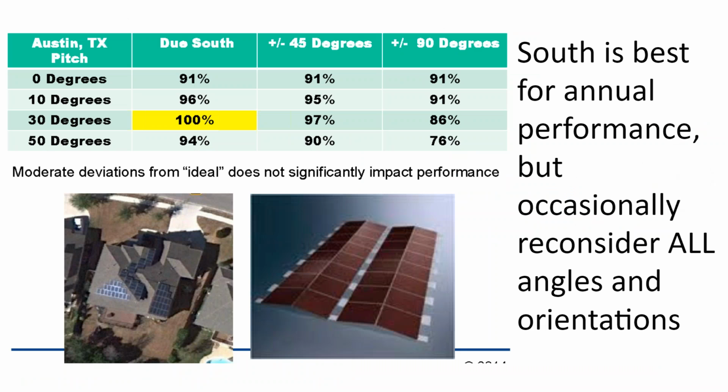And you say, well, JR, you're saying 1 watt will produce 1.4 kilowatt hours, but what about how you point the array? Doesn't that vary the production? And the answer is yes. How you orient the array does vary the production, but not as much as you might think.